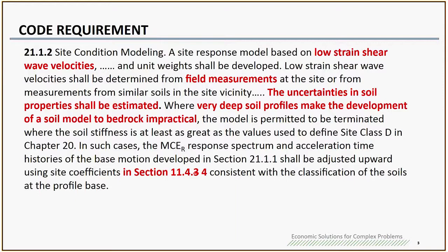In the code requirement, there is a typo. The site coefficients should be in Section 11.4.4, not 11.4.3. That's the old section in the ASCE 7-10.